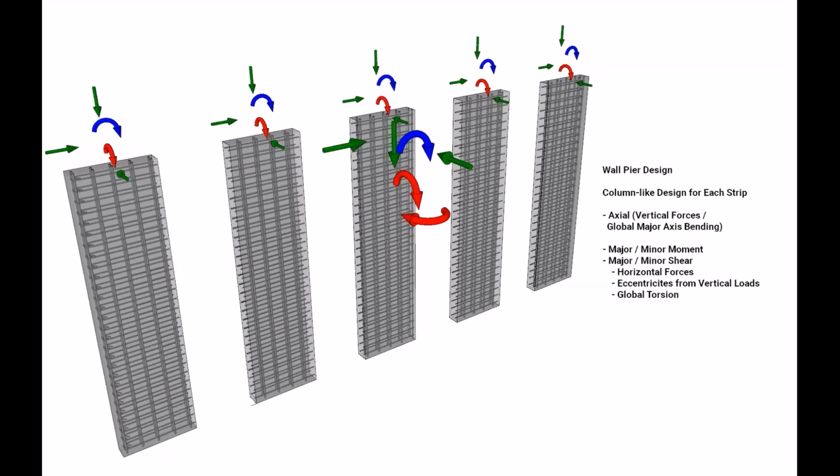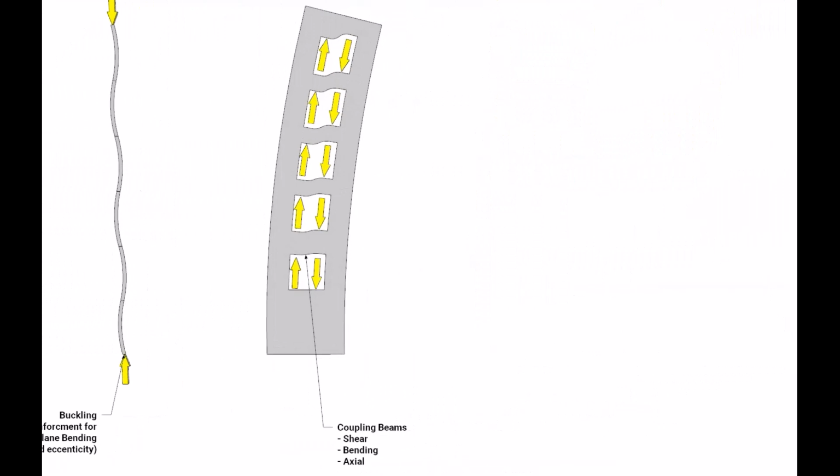So I've mentioned coupling beams earlier. I'll jump back into the failure mechanism slide so you can see the deflected shape on that last diagram with the opening. So here, the coupling beam behaves as a fixed beam, so it transfers moments, much like a sway frame, but also axial loads to distribute horizontal forces between the vertical piers.